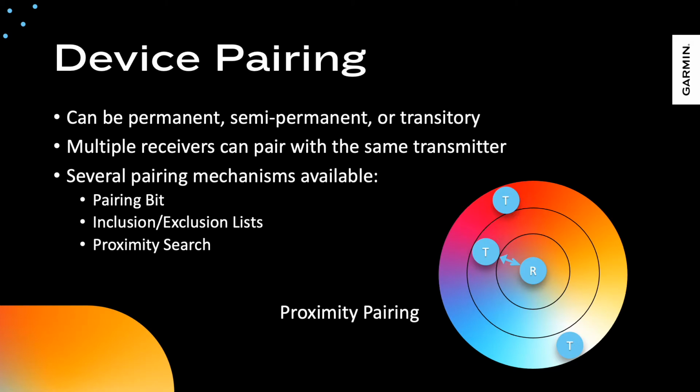If, on the other hand, the receiver does not know the exact channel ID of the device it is trying to connect to, it can use a wildcard search. A receiver can wildcard any of the channel ID fields by setting them to 0. So, if, for example, the device is trying to search for a heart rate sensor, but the device number is not known, the device type can be set to the heart rate device type, but the device number can be set to the wildcard value.